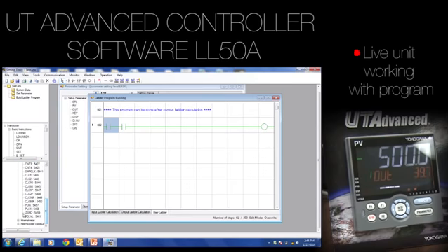So we want an always on register. Let's pull that over, and I can either double click here and type that register in by typing in PLS, and it's going to give me a list of everything that starts with the characters that I've typed. Once I get down to the point where I know what I'm looking for, I just hit the enter key, and that shows up there. The other thing I can do is just click and drag. In this case, I've got a 1 second clock. I can click on that and drag that to that relay input, and there we go.